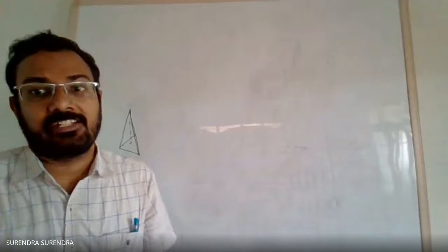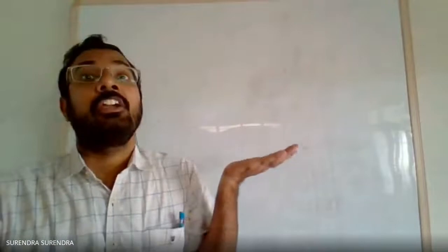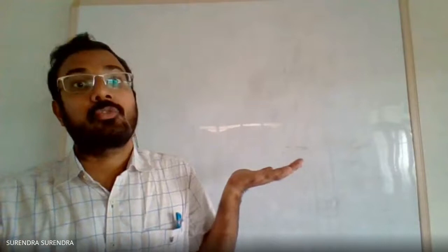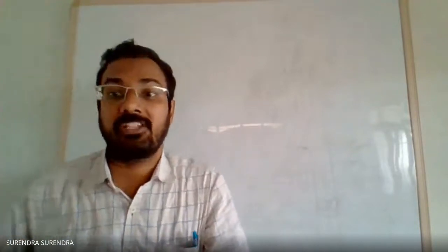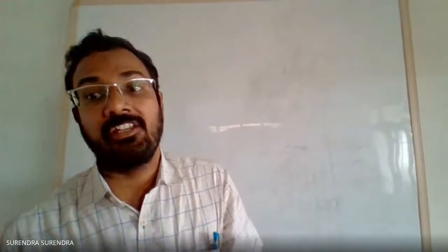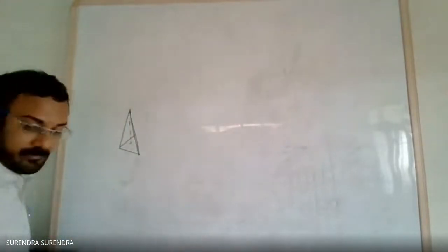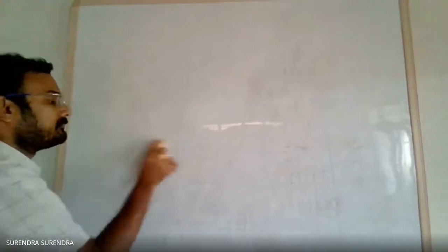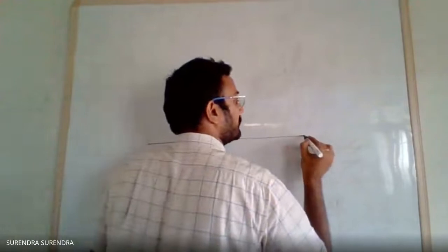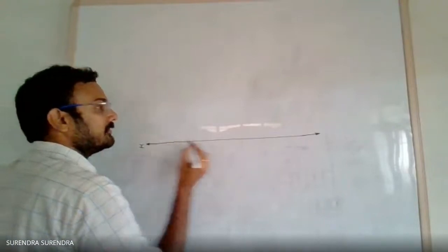A tetrahedron of side 60 mm is resting on one of its faces on the ground. Means in the top view you can see the true shape of the base. And for drawing, what are the other conditions given? With an edge of that face inclined at 40 degrees to the vertical plane. So you must draw the tetrahedron base in the top view. This is the simple position.